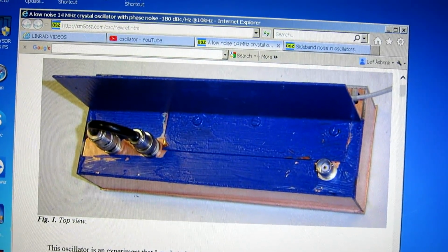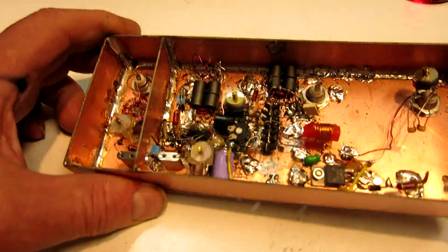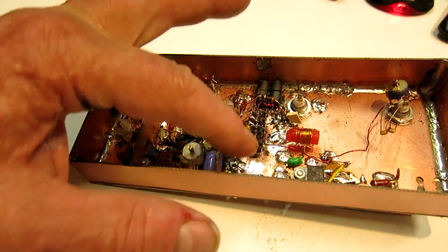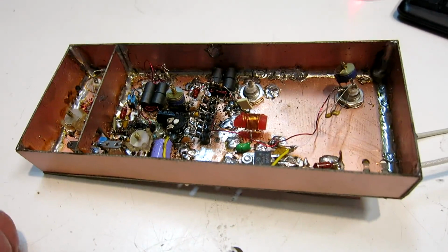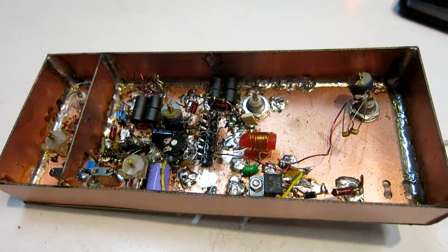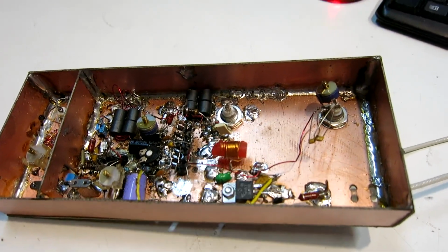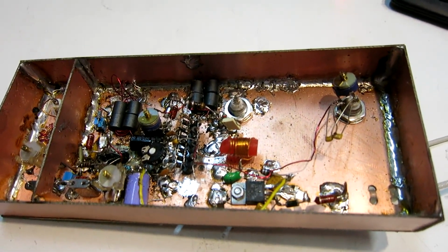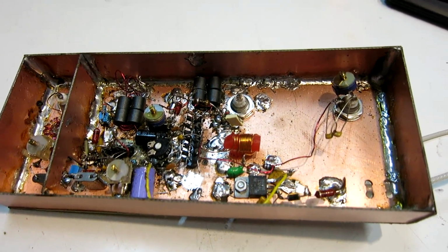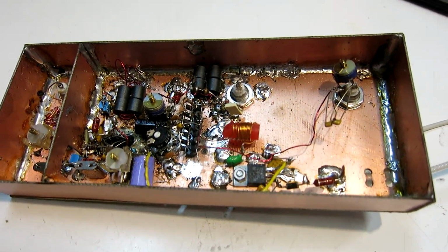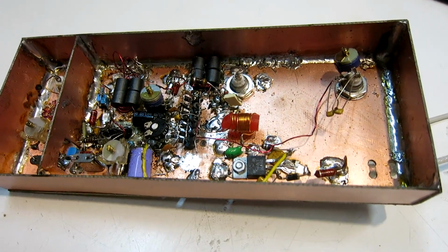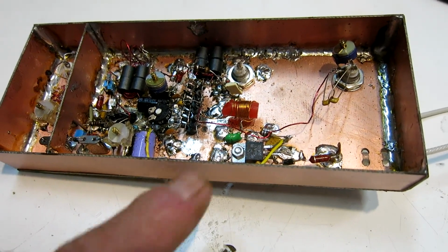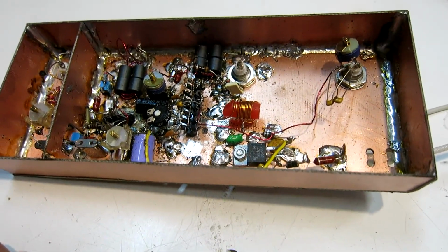So in order to do that, I built this unit, where you can see I have 6 transistors in parallel. There have been crystals here, and I had difficulties with this. First there was a transformer here, and there were some peculiar sideband noise oscillations of some kind. So I decided, well, that could be parametric oscillations due to the ferrite. So I changed the output for iron-free. That didn't help.